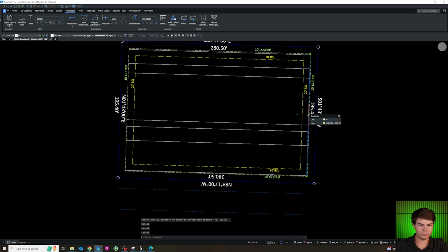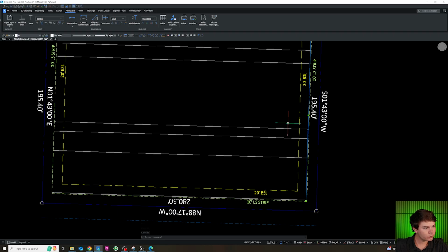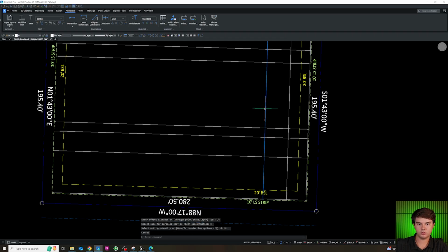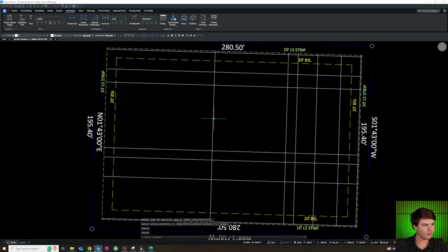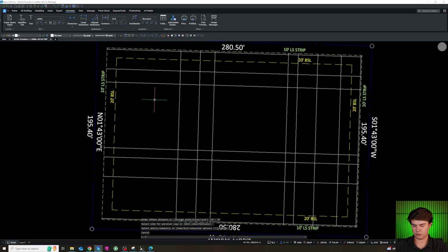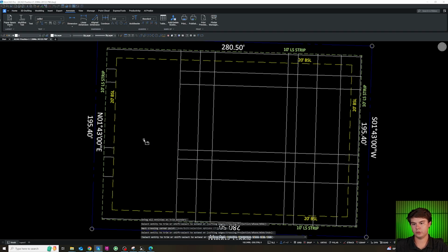And then from our east constraint, we're going to have 20 feet of parking, 24-foot drive aisle, 20 feet for more parking, 10 foot for sidewalk, 75 feet for building, 15 feet for more sidewalk, and 20 foot for drive aisle. Now this saves all this room over here for our detention pond.